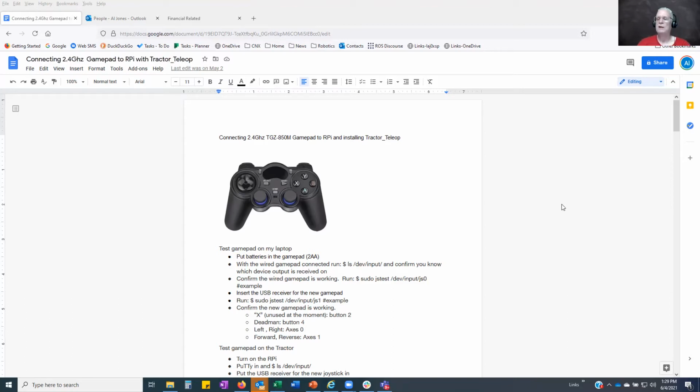But as we also talked about the last meeting that didn't get recorded, when you've got two computers connected together on ROS, you can put nodes anywhere you want and it will still work. You can put half your nodes on the base station and half on your robot, and they will connect together and all work just fine. And we also discussed the fact there doesn't seem to be anything that tells you that that's what's happening.